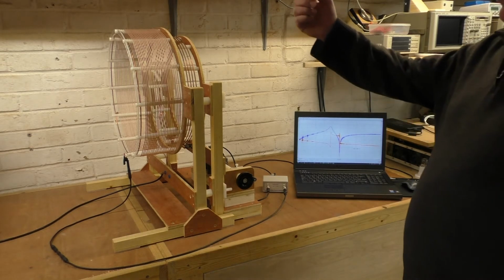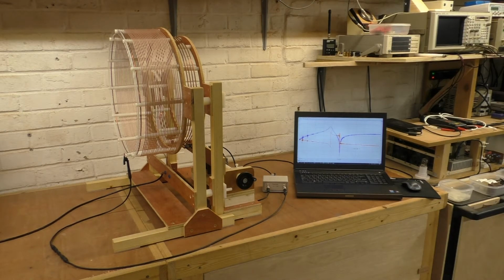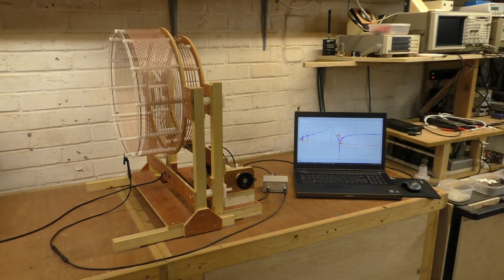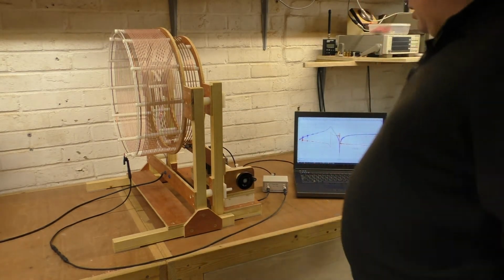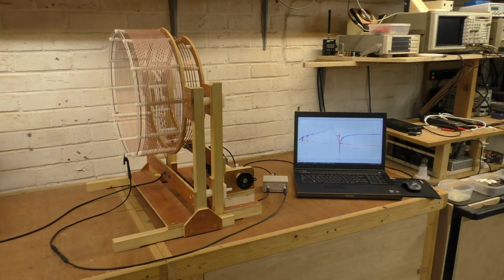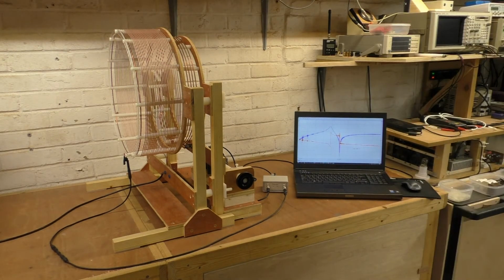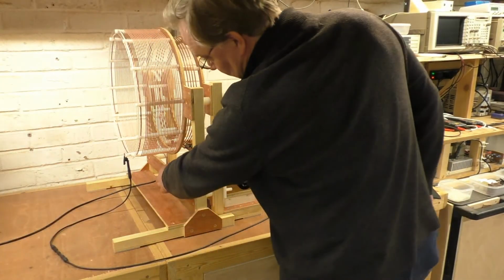Nominally, the series resonant, fundamental resonant frequency of the secondary coil is at 1.95 megacycles. So that's right in the 160 meter amateur band, and our connections both to the input and the output are very much shorter than even the wire length. This is a quarter wave resonator, so we're operating it with this wire coming at the bottom of the secondary coil.